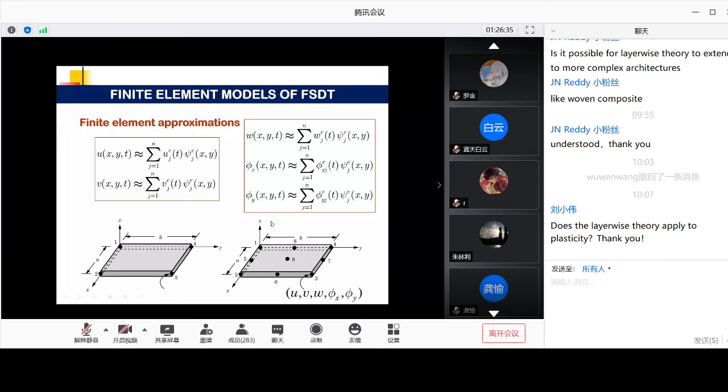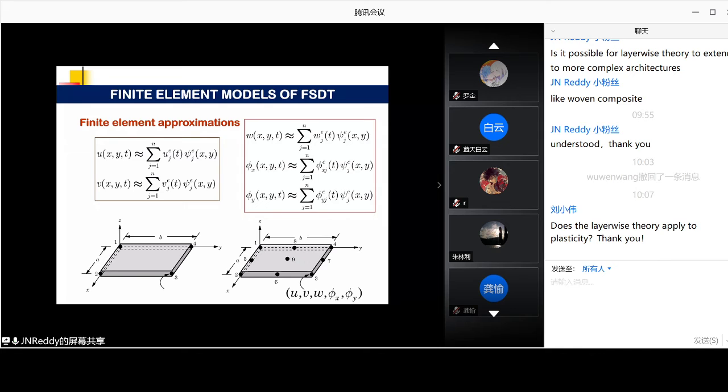It is part of the need, because you want to also solve problems where the plate is folded or L-shaped. Then what we call rotation about x and y axis in one part of the plate becomes rotation about the z-axis in the other part. So you need 6 degrees of freedom at each node to solve real-world problems.